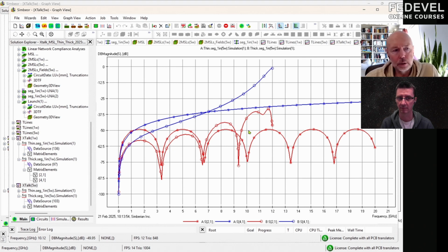And some advanced signaling standards like Ethernet, OIF, chiplet interconnects, for instance, they have compliance metrics for crosstalk. So essentially in Simbeor you load those compliance metrics, and there are presets for such standards, and then you compare. And I can show you how it can be done on a real board if you have 5 minutes. If we have time, yeah, we can do that.